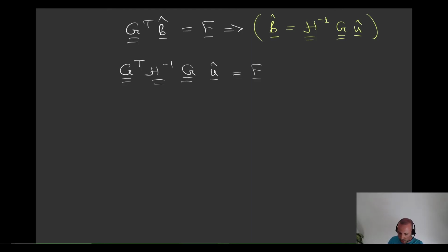And now here, please note that we have an equation system that looks exactly like K times U is equal to F, right? It's the same thing. But in this case, the K is a little bit more elaborate. So that is the K here that we have, the system matrix, so to say. And you see that in order to obtain this system matrix, we need to invert another submatrix of the initial system of equations we had. And so in this case, of course, the system is a little bit more elaborate from what we've seen already in the first chapter, in the classic variational formulation of the Timoshenko beam problem. So of course, we're going to have a little bit more elaborate computations in this case. But nevertheless, that's exactly the linear equation system that is associated with the Hellinger-Reissner formulation of the Timoshenko beam problem in this case.